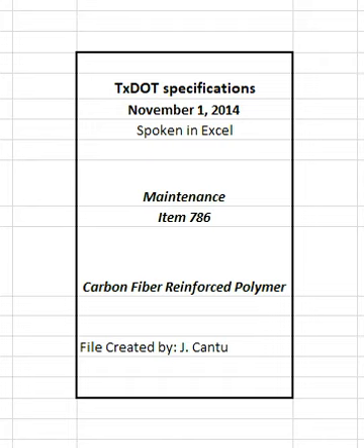Table 1. CFRP carbon fiber property requirements. Property and specification requirement. Tensile strength is 550,000 psi. Tensile modulus is 33 million psi. Ultimate elongation is 1.5%. Note 1: Verified by ASTM D3039 test procedure.